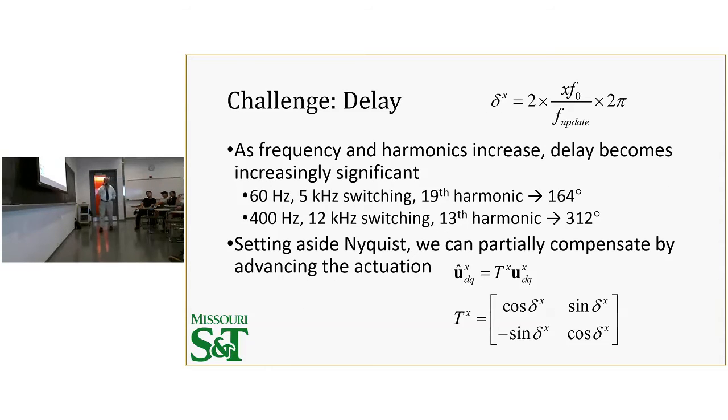Okay, so I mentioned that delta. The problem with this is the delay. Now, when Pat was doing this back in the 90s, he was only concerned with maybe out to the 7th harmonic of a 60 hertz waveform, switching at like 10 kilohertz or something. And so he didn't have to deal with this issue. But if we look at the 19th harmonic of 60 hertz, if we only have 5 kilohertz switching, 1 unit delay is 164 degrees.